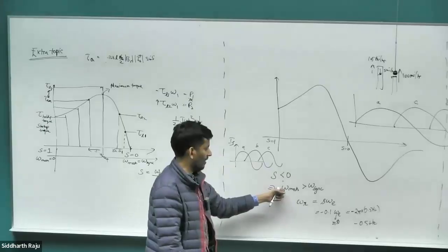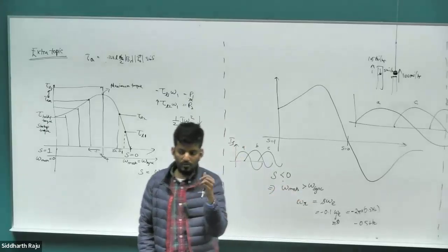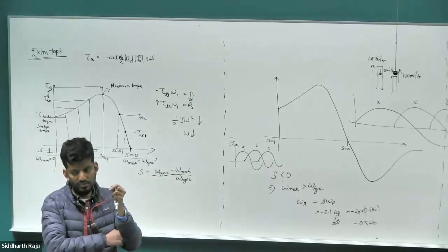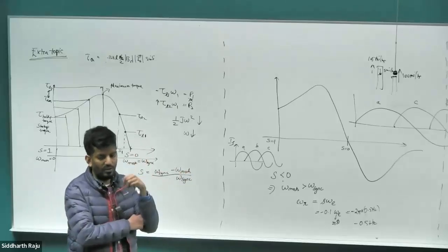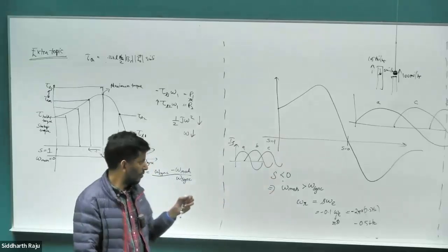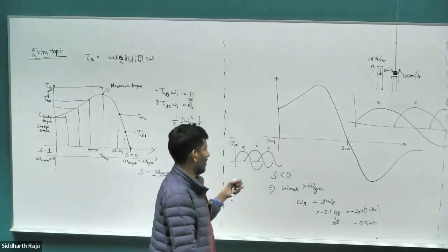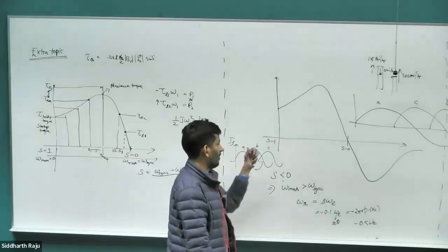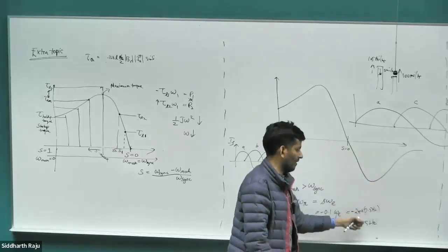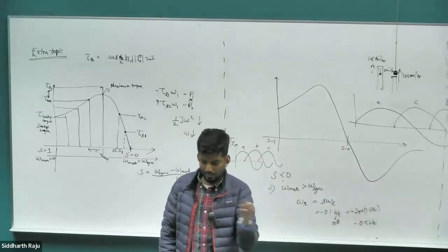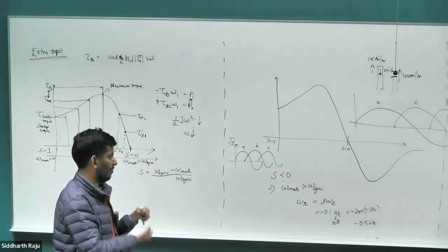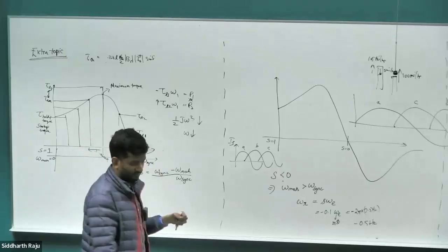And the rotor itself is rotating at, instead of 50 hertz, it's rotating at 50.5 hertz. And then the space vector is rotating in the opposite direction with respect to the rotor at negative 0.5 hertz. So we end up with the total speed at which the space vector is rotating being 50 hertz. So this is the same speed at which the stator space vector and all of those are rotating. So this is what generation mode means in an induction motor, where the rotor sequence component basically flips itself in such a way that the slip ends up becoming negative and the frequency is interpreted as being negative. And this is exactly the same as what we saw in the case of the permanent magnet synchronous motor, where we change the direction of rotation by just flipping the phase sequence.